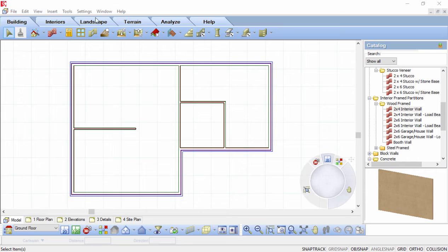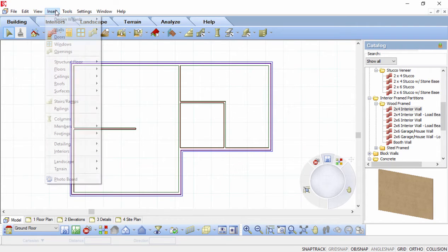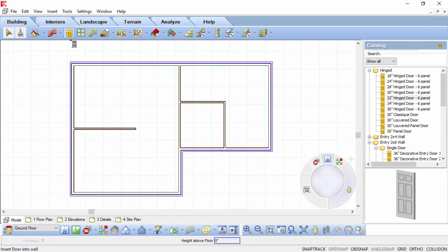You can insert a variety of doors with point-and-click simplicity. Because doors are intelligent elements, they fit themselves into walls and become part of them automatically. However, you can edit doors separately from the walls that contain them. We'll insert 3 doors in our design. Select Insert Doors, or select the Building Toolbar tab and select the Doors button.